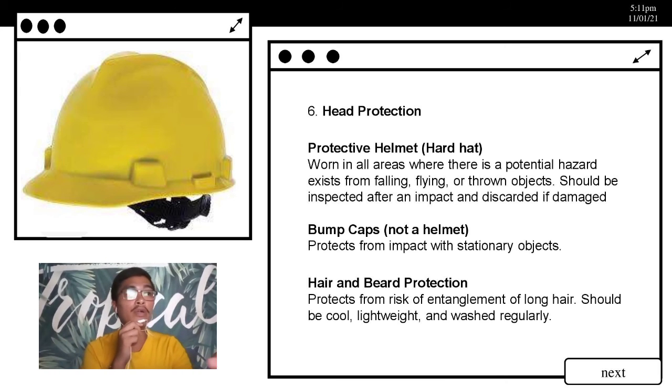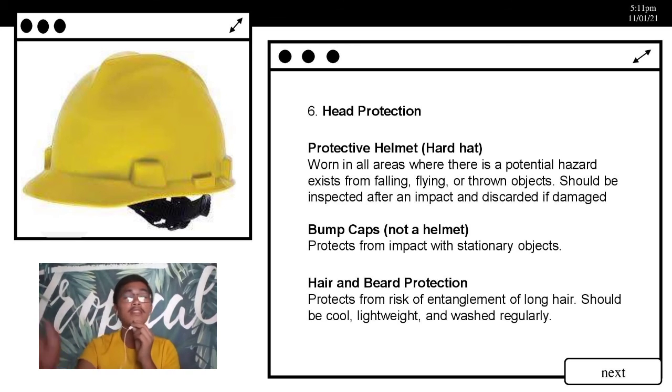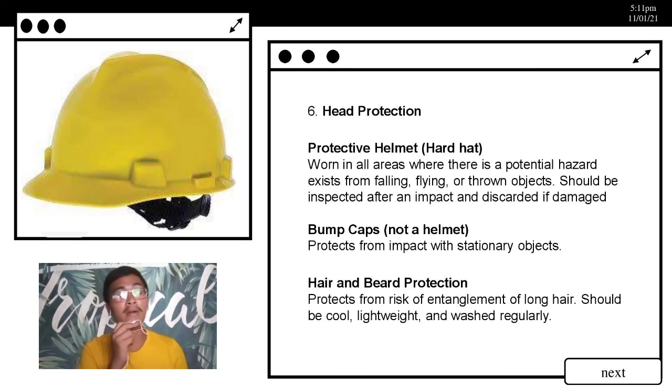So next is the class G or the general type of electrical hard hats. These are designed to reduce exposure to low voltage conductors and offer dielectric protection up to 2200 volts phase to ground. So as is the case with class E hard hats, this amount of voltage protection is designated to the head only and does not count for voltage protection allocated to the user as a whole body. So same with the class E, it does not protect the whole body but the head only.